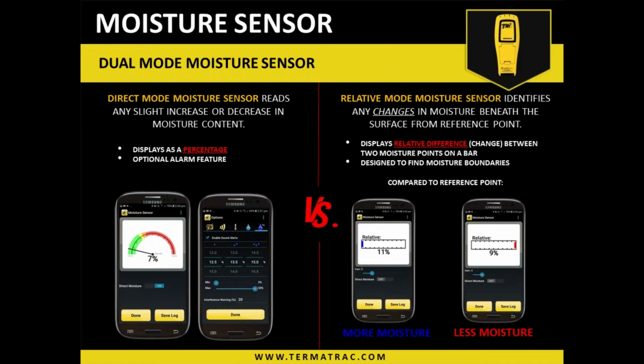We can have alarms set up. There are 3 stages of alarms, and those stages are individually set. It's for you to set up with your understanding of what the equilibrium moisture content values are within your region. It also depends upon how much rain we have or the ambient humidity, so that will continually change.